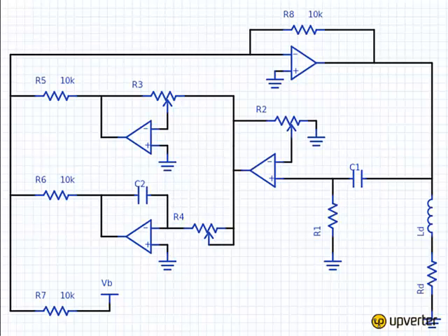We then amplified that and put it into proportional and integral control stages, and then we added the two of those currents to a bias point, VB, in the bottom left, to create the output voltage that we set across the inductor system. This did not quite work as well as we had hoped.